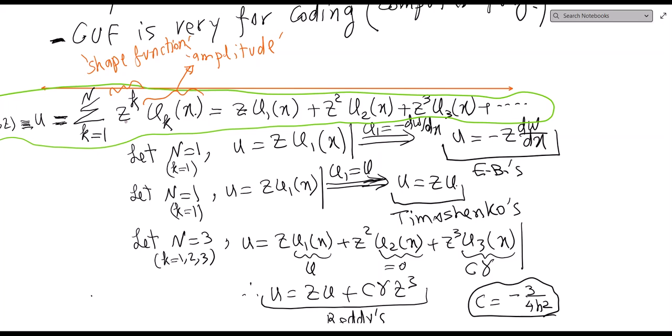So at each section, for example, if I consider this one, I said this is linear, and this is my amplification. How much any material point located at Z on my plane perpendicular to my neutral axis will move. It will move by phi 1. How much that same point Z will move as a quadratic or parabolic polynomial. This is this much. How much of it will go according to a third order or cubic warping?